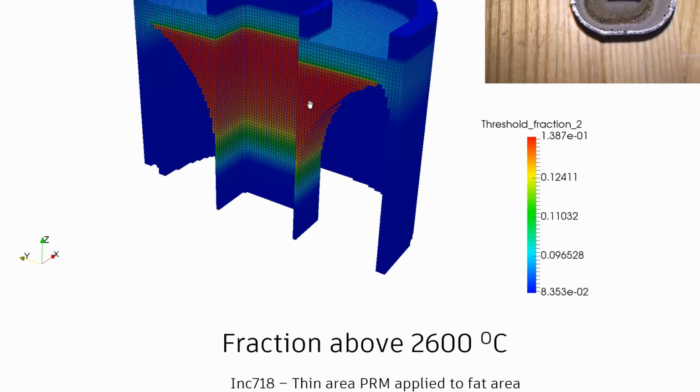However, as you move to the fatter sections that you see up top over here, you can either speed up your laser or lower down the power, because you now have a lot more cross section that you're burning with the laser, and you don't need to operate at the same parameters as the thin area. But if you choose to do it over there, you're going to end up increasing the temperature too much.